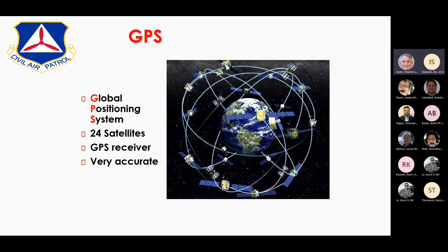Firstly, as we'll discuss later in search patterns, we fly our search patterns at 90 knots. That's 90 knots ground speed. If you've got a typical 10-degree wind like that we often have in California, then when you're flying in one direction, you'd be doing 80 knots of ground speed, even though you're indicating 90.